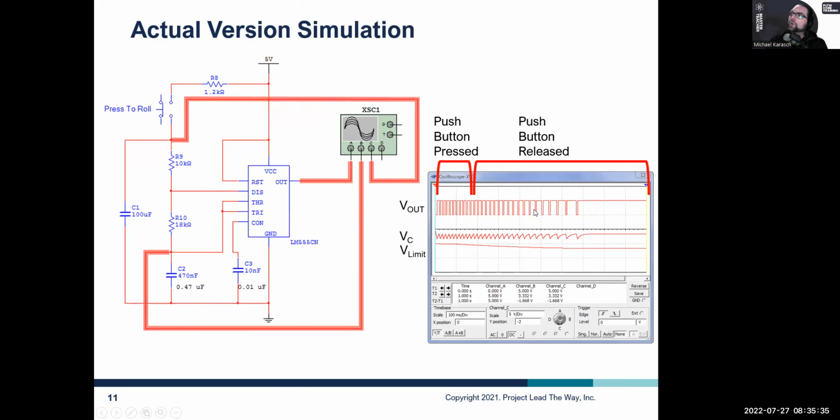So here they show you on the oscilloscope what this should look like, and you are actually going to measure this. You're going to have this circuit built, and you're going to measure the wave early in the beginning here. We should see a very small period, very high frequency. Then you're going to measure it somewhere in the middle over here, and we should see a larger period, smaller frequency. It's slowing down. And you're going to measure the last wave right here before it flatlines, and we should see the slowest frequency. So you're going to measure in 3 different places to demonstrate that it's slowing down. That's part of what you're going to do in the activity. And I'll show you.